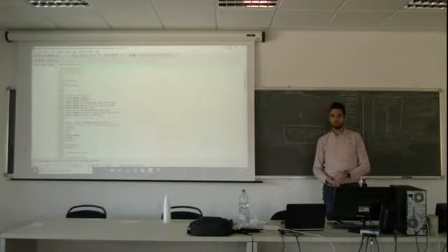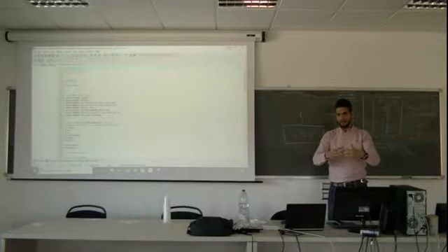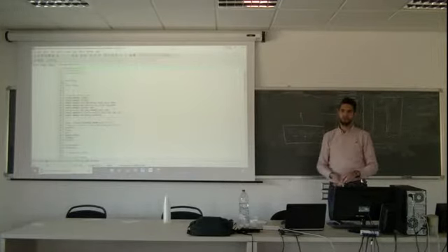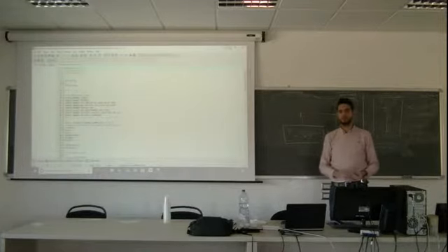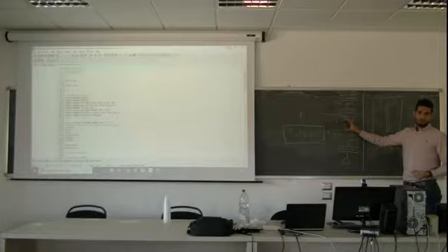In any case, mass conservation and momentum conservation usually use 0.6 as a relaxing factor, 0.5, 0.6, because the physics are more difficult, more complex, so you have to relax more, not to jump over the solution. But the energy equation usually 0.9, 0.8, it's okay. So is this clear? Yeah?